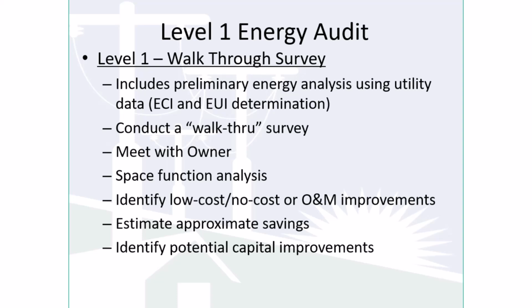When you get more experience, you will understand the value of, especially, an EUI. If you have a facility that's an office building and it has a relatively high EUI, then that gives you a clue that, hey, this building might be in need of some improvements. If it's already performing really well, then you might have to look a little deeper. So the EUI is a very good calculation.